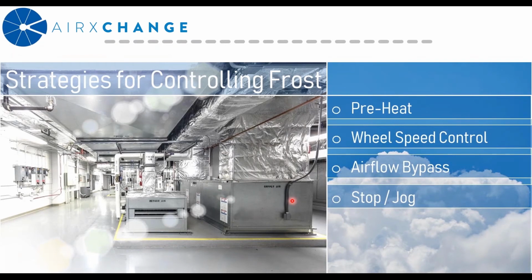So now that we've generated a process that could result in frost, what are the popular methods to allow a wheel to work in these conditions? The four most common strategies in the market are preheat, and I should mention that preheat is the only method that I'm going to discuss today that allows the wheel to operate at its full potential in these conditions.